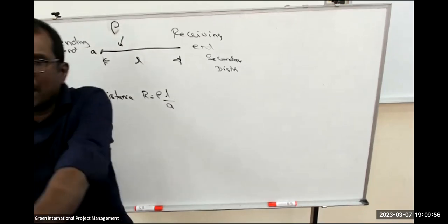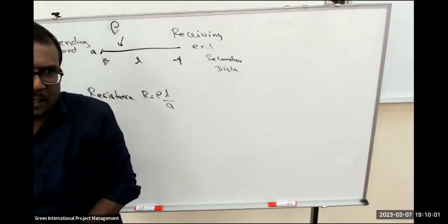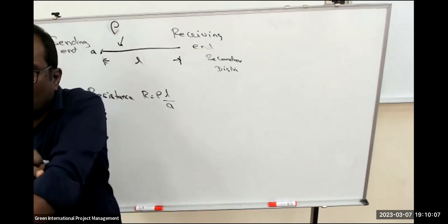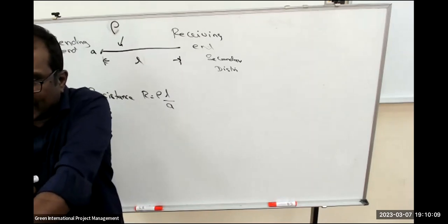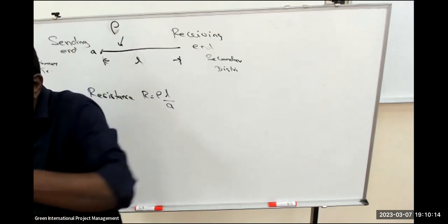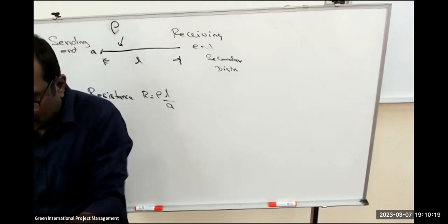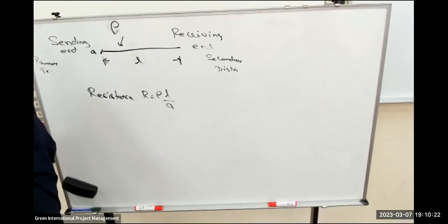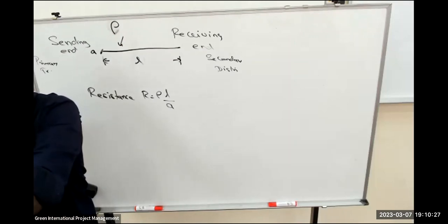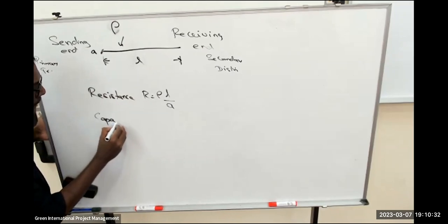Assume that we have the R phase, Y phase, B phase, each a conductor. Two phases are there, and they carry the power. We are transmitting AC power, so it carries AC. In between these two conductors we have air present. We are not putting the air there, but we are laying the conductor in the atmosphere. The air is just like a dielectric medium, which means it acts as a capacitance. So in the transmission system, we have a capacitance.